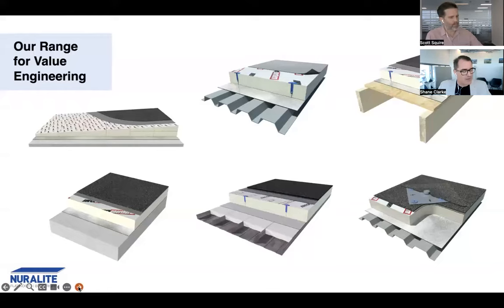Again, the substrate, whether it be a metal tray substrate or a plywood substrate or a concrete substrate, those are things to consider as well. Also, an efficient thickness of PIR board. While it's great for sales to have a 300mm thick layer of insulation, we can actually help out with the calculations and say that that's absolutely unnecessary and overkill on that building. So we can actually maximize the efficiency with the required R value that you're aiming for.